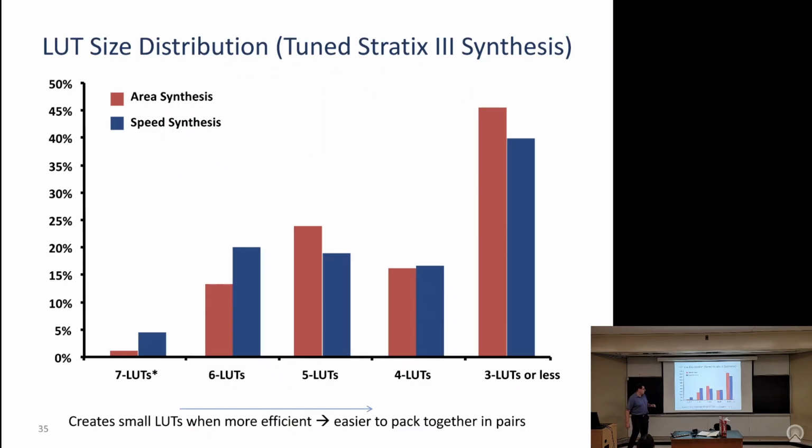But it turned out that there were certain uses for some of those. One of those 7-LUT functions was useful for building multiplexers. And multiplexers show up a lot in design logic. So there's a few things called 7-LUTs. They're not really a LUT, right? But no one in the marketing department is going to try to explain that distinction to customers. They're just going to say 7-LUT.